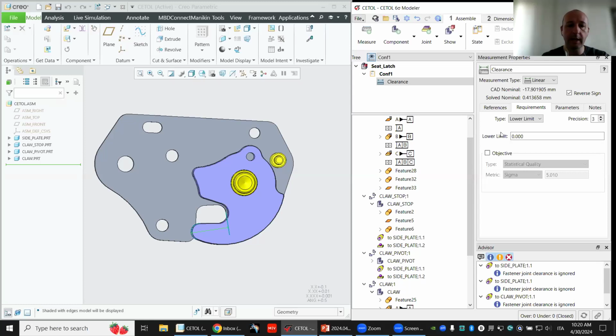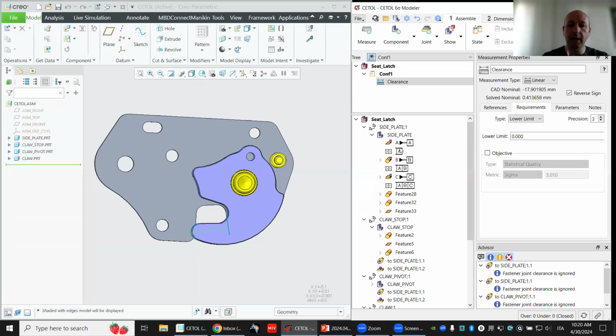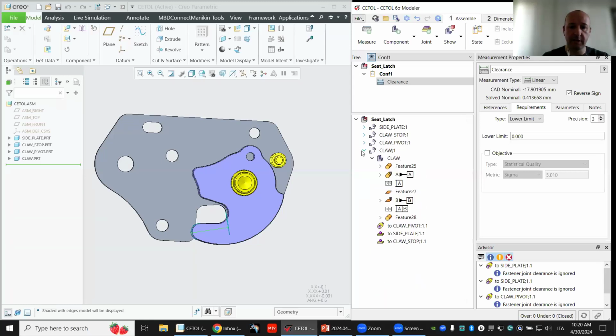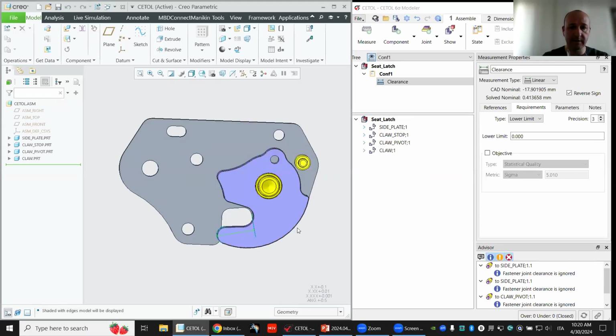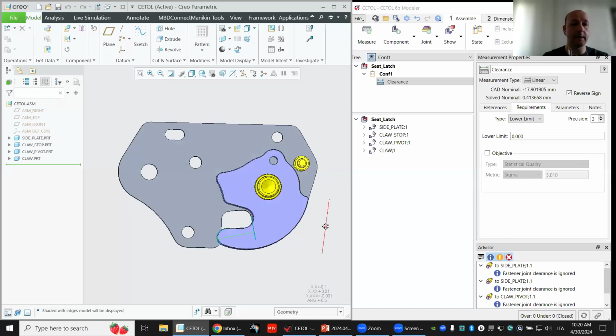And now we can move to the calculation of my tolerance chain, and take a look at the final results and discuss the most important topic, that is the definition of the corrective actions that we can apply during the design phase of this product to obtain a robust design from the tolerance propagation point of view.